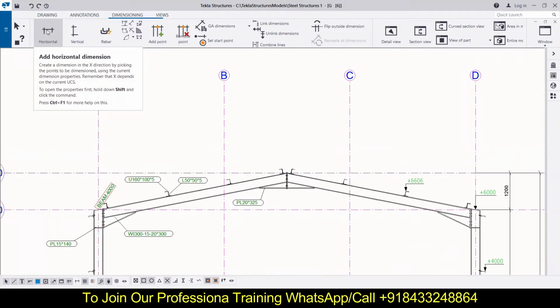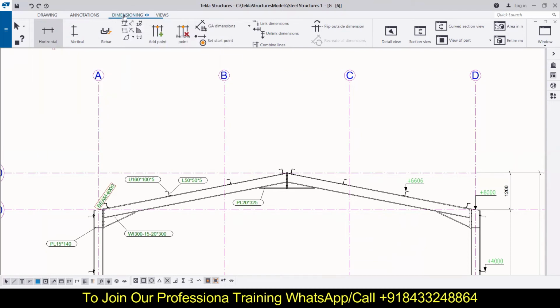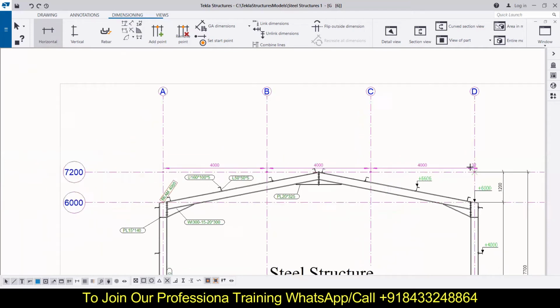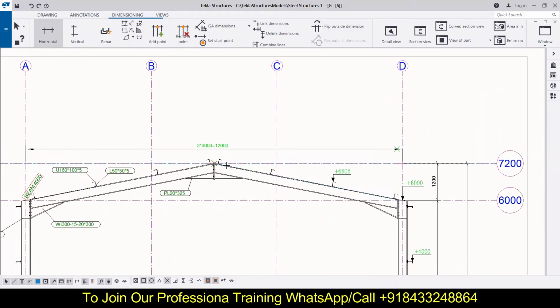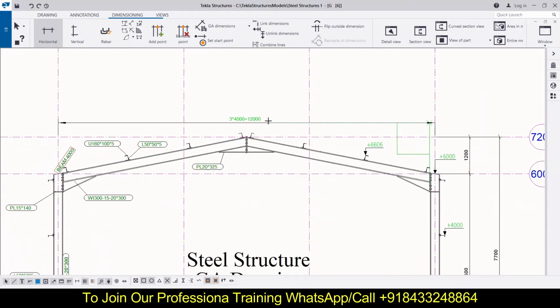So what I'm going to do over here, I will just click on the horizontal over here, which is coming in the section of the dimensioning. Okay, so go to horizontal, and over there you can just mark the dimensions like this. Okay, so all you have to do is to just move like this, and then you will have to press the scroll button of your mouse and all the dimensions will be placed. Okay, so you can see we have this format of dimension.